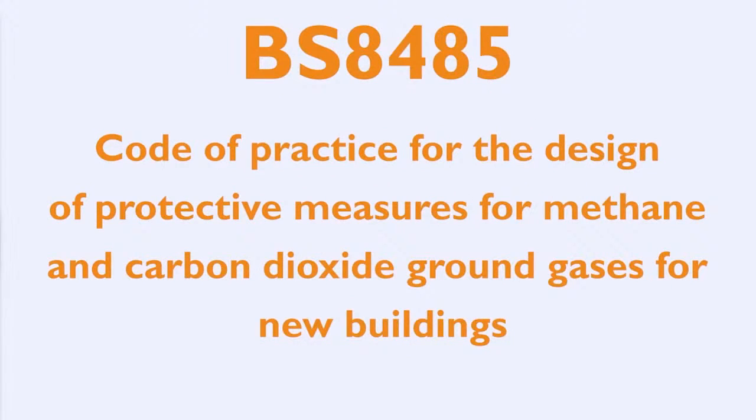BS 8485 is a code of practice for designing new buildings and conducting risk assessments on proposals. It was originally issued in 2007 as a 28-page document. However, after a revision in 2018, it has now grown to about 100 pages. BS 8485 bases its guidance on site classifications from CS1 to CS6.